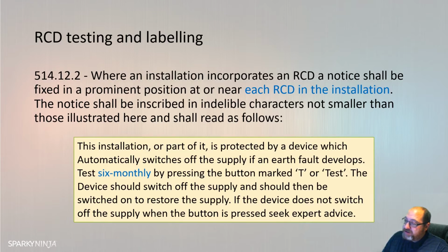The notice shall be inscribed in indelible characters not smaller than that illustrated in the book. So no smaller than what's in the book. We then have testing frequencies of the RCDs, as temporary installations may need increasing because of the dependency on RCDs in temporary systems.